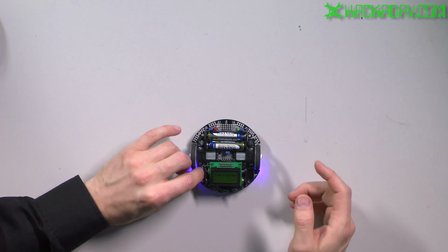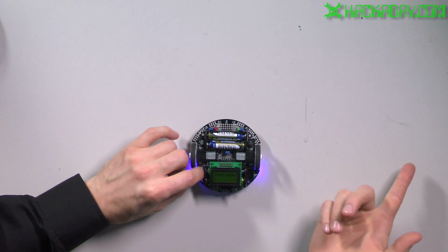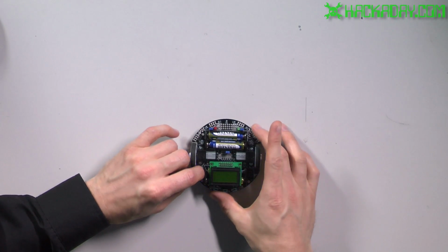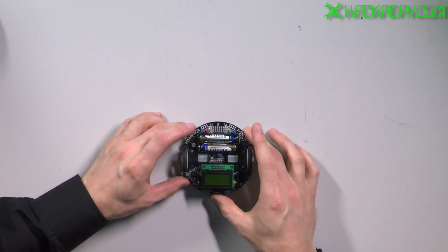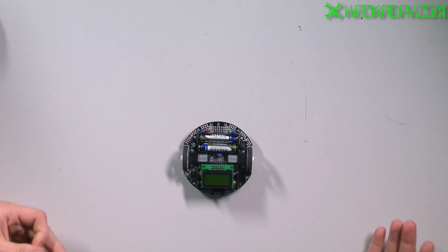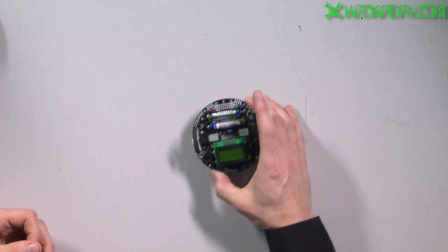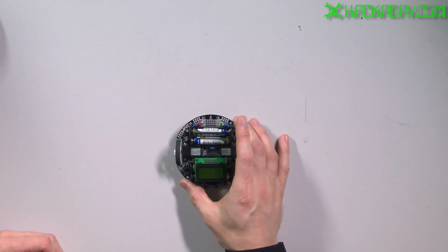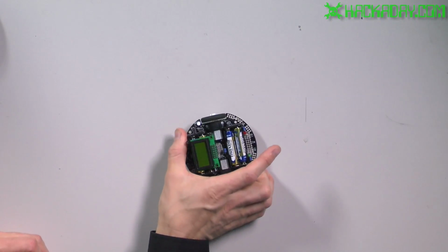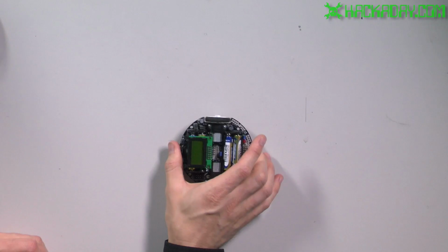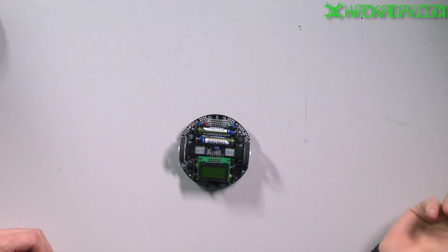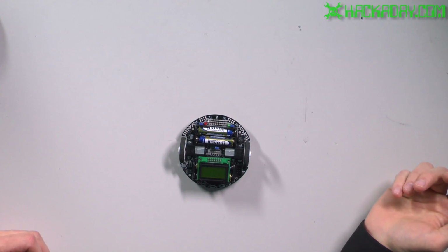If you were doing the other type, where it's sign magnitude, I believe is what it's called, you would not have that if it's stopped. But again, I did this because I feel that it gives you better precision. And let's say we wanted to do something like maze solving. You want to be able to make repeatable, nice turns, and this type of pulse width modulation will allow you to do that. So that was pulse width modulation on the ATmega328P processor. This is Jack Buffington for HACKADAY.com.